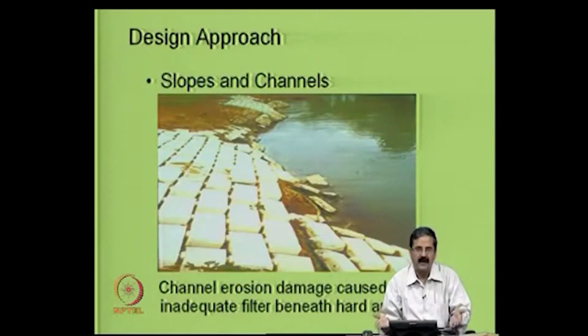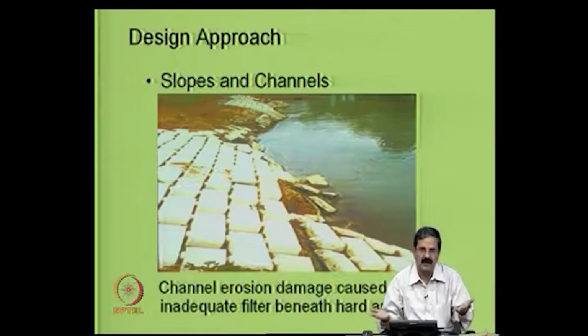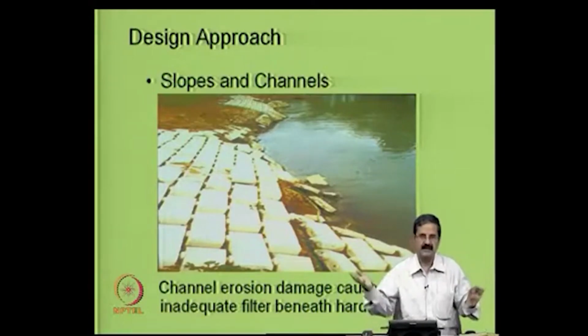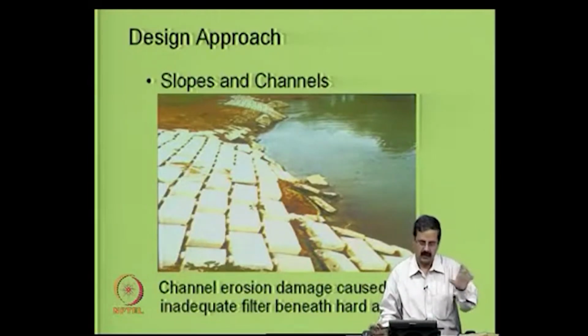When they thought that they should increase the water in the lake, they pumped in and tried to store a lot of water in the tank. As a result, the tank water level was fine, it just went up, but along the footpath, in some places the footpath got totally inundated, so it became useless. In some places the retaining walls got overturned, because the retaining wall didn't have proper drainage. That was a serious issue, because the base of the retaining wall also gets saturated, and erosion can come.